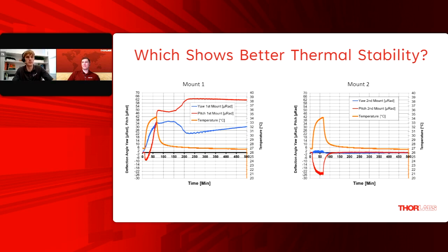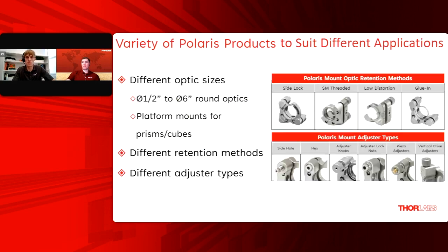As far as lockability, I'll show our slide here. I think this hopefully is the best picture to depict that, but we do have lock nuts for all of our adjusters. While the front plate itself is not technically locked to the back plate, the springs are very stiff and will hold that in place, especially through the shaker plate testing like you saw before. But when it comes to shipping these elsewhere, where you don't want the screw itself to move and thus move the front plate, we do include lock nuts. And online we have different torques for short-term and long-term shipping or locking as well. So these are thoroughly tested for different shipping constraints and locking over time.